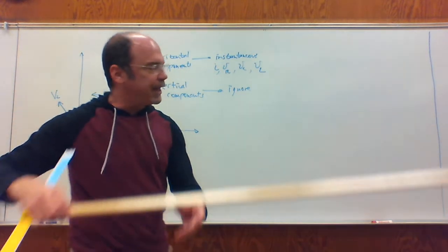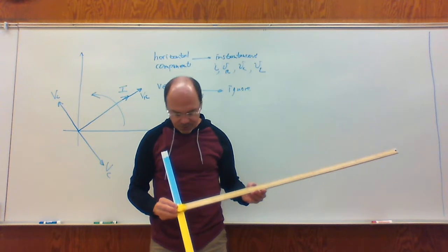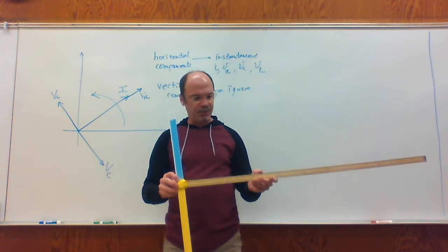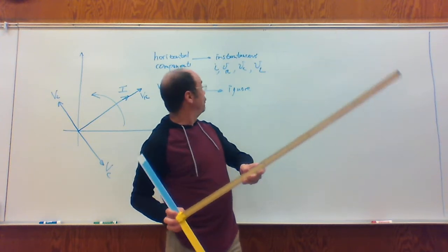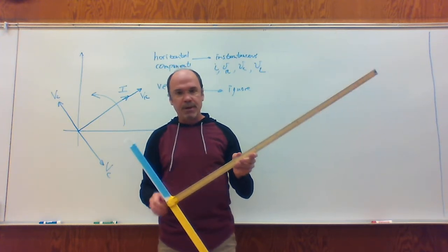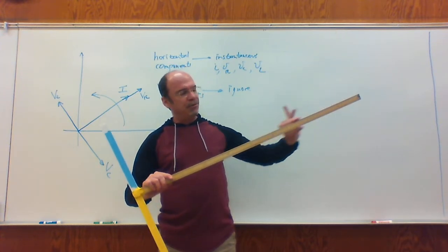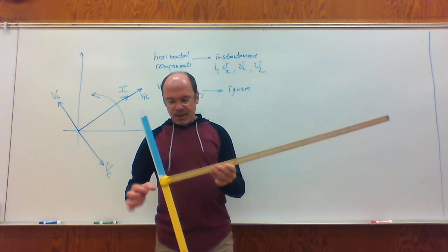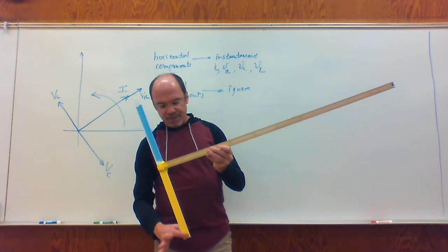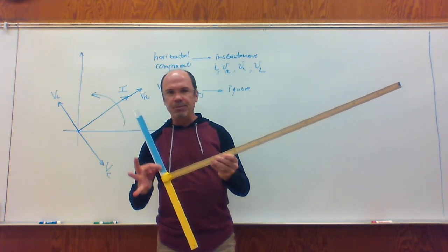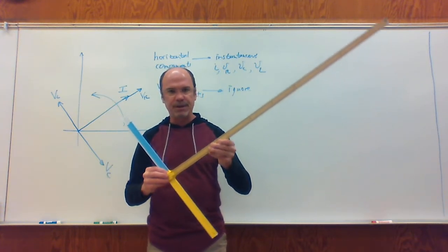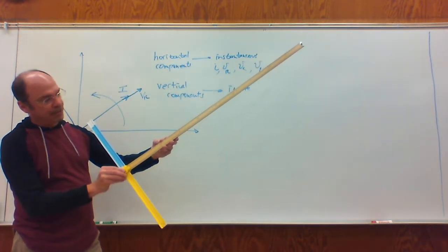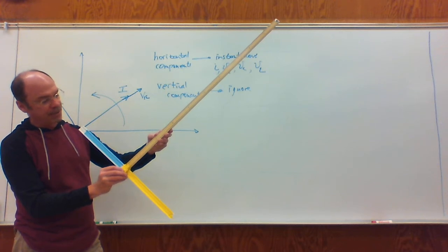And since I can't do this on the board, I could simply illustrate what's going to happen as this thing rotates. From your point of view, it'll be rotating counterclockwise. So this will be the current as well as the voltage magnitude across the resistor. This will be the voltage magnitude across the capacitor. This will be the voltage magnitude across the inductor. And so the way I have it oriented now is identical to what I had on the board and most likely what's in the book.